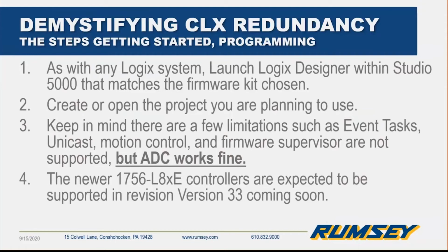Those of you that know how redundancy works, in the L7s and previous versions, you have to have enough memory and double it when you go to redundancy. The L8 rids that. So we're not going to have that kind of consumption of the memory, because one of the cores in the L8s takes care of that. It is expected that we will not be able to use the onboard Ethernet port on the L8 on the first revision of 33. Other than that, it's very, very exciting that we're going to start supporting these controllers.